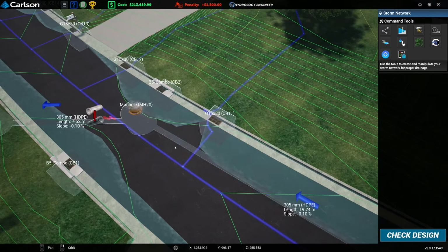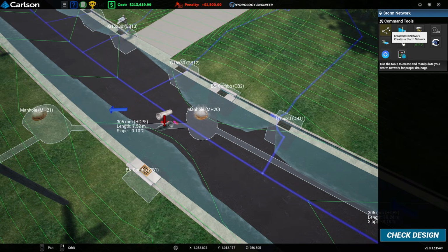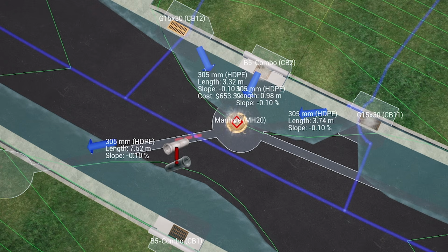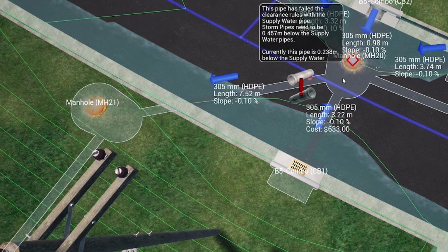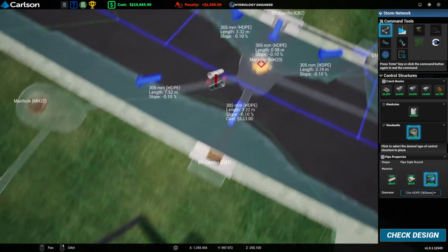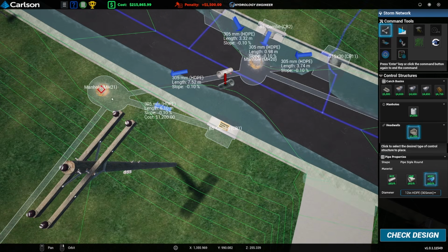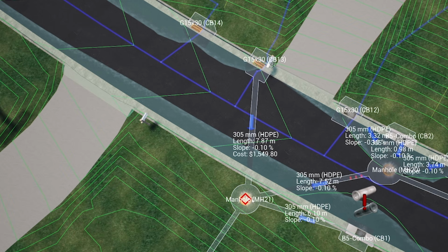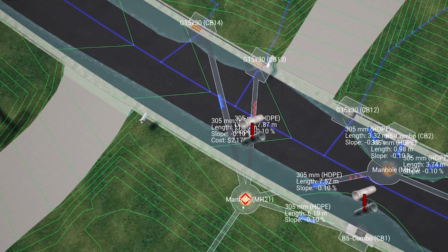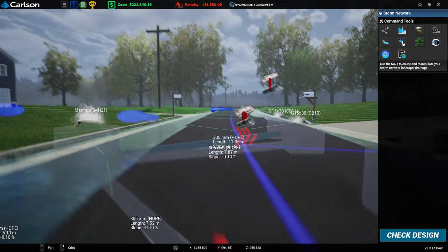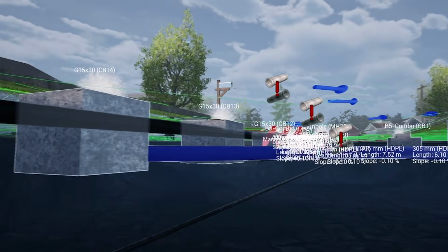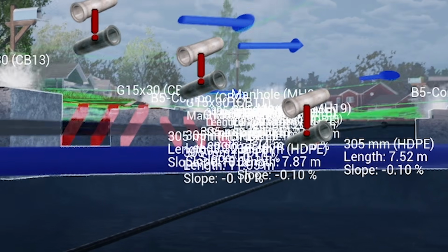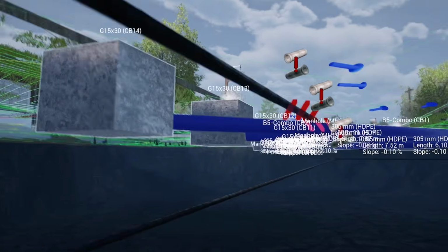All right, so anyway, down here we haven't actually connected up our gullies yet, so we'll just connect all of those pipes in. This pipe I'm going to go over to that manhole rather than that one, just because of the angle. You generally want to keep it like 90 degrees so water's always flowing towards the outlet. These gullies I can connect straight down to there, but as you can see, they are clashing with the pipe. They're not technically clashing, like if you look down that pipe, excuse all the numbers up there, absolute carnage. They're not technically clashing, but they're way too close.